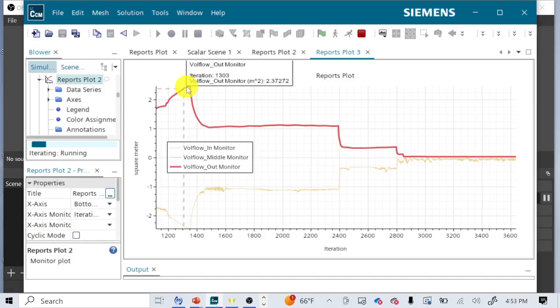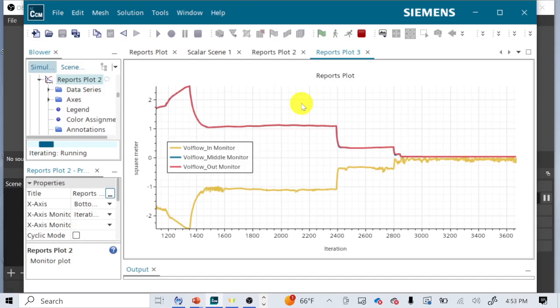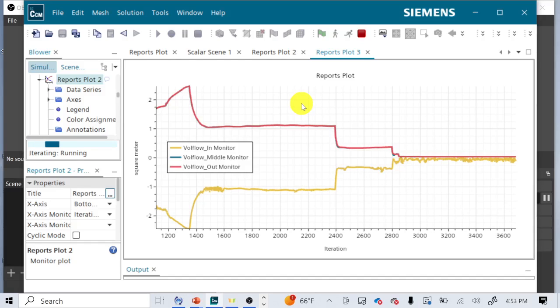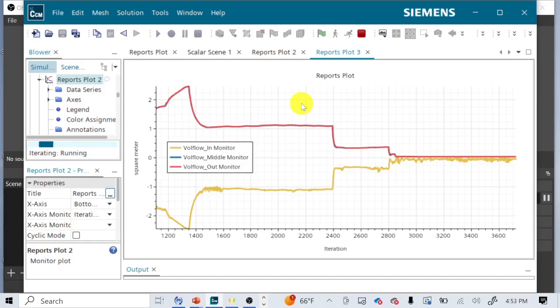And it actually seems to work reasonably well at moving air from the looks of this. Now this is 2D. What's the limitation of that? How does it get a volumetric flow rate if it only has 2 dimensions? It assumes the z direction is 1 meter. So, to be fair, this is not a small fan. The fan is a foot across and a little bit over 3 feet long. So this is not a small fan, but it is moving quite a lot of air. So, in that context, that number does make some amount of sense.